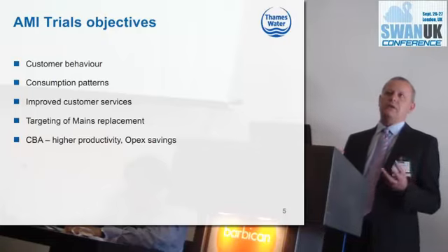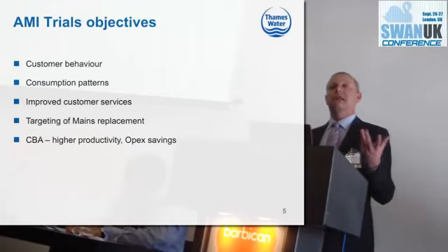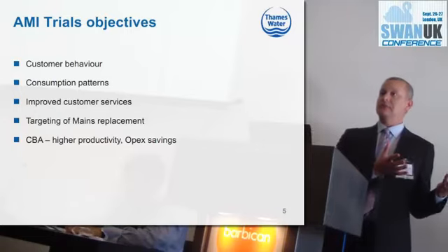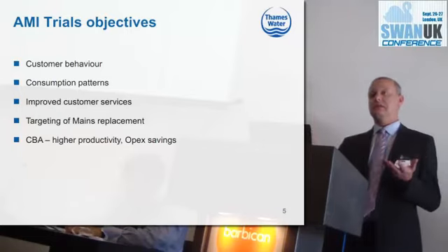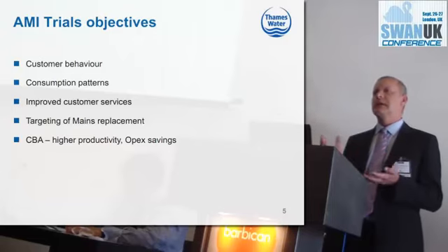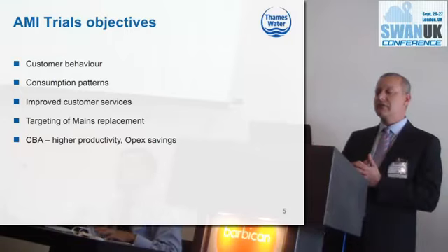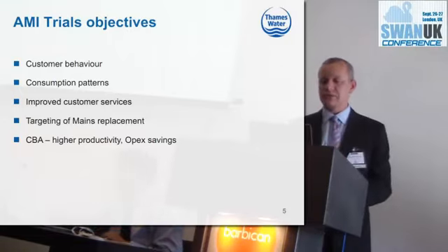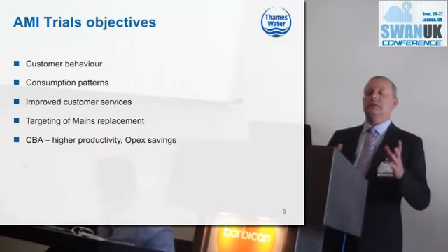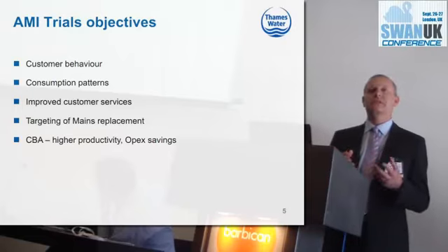So now if we have a whole area with everything metered, and we have an accurate water balance, we will be able to say that actually our network is not too bad. So the leakage is customer side leakage and not network. This is one of the key things where we could find real benefits, in the investment for mains replacement. And along this trial, during the whole period, obviously we are going to investigate a cost-benefit analysis,